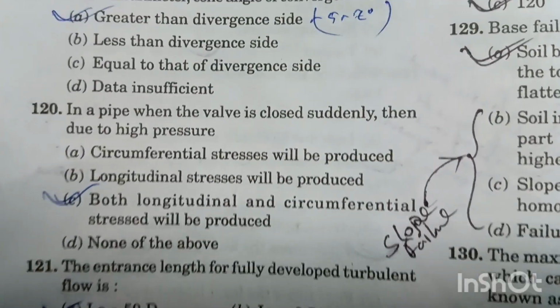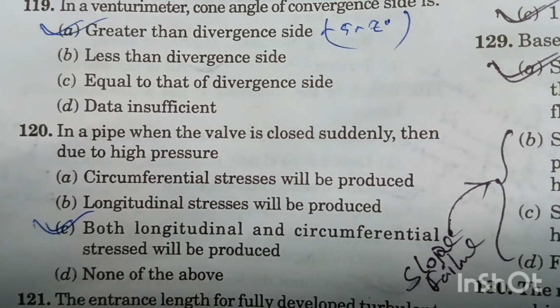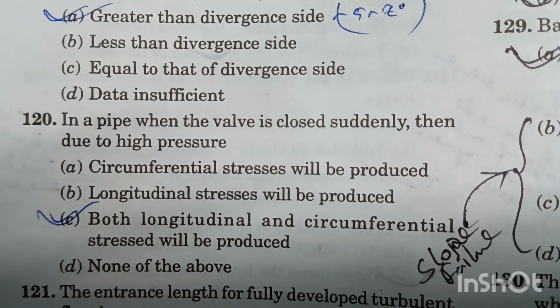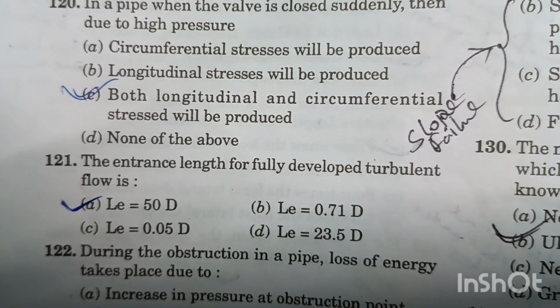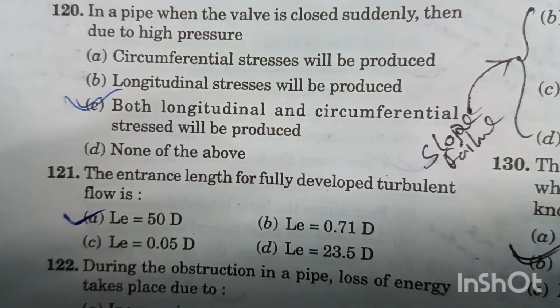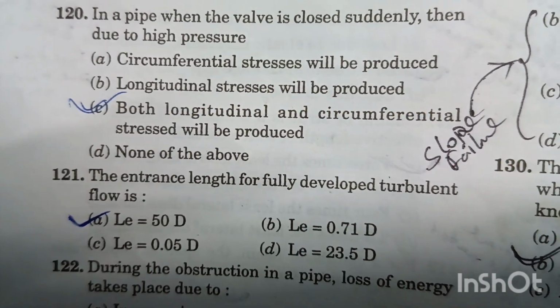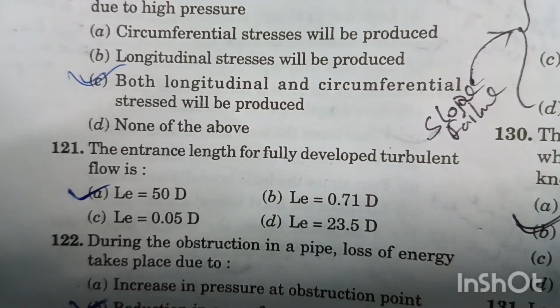Question number 120. In a pipe, when the valve is closed suddenly, then due to high pressure, both longitudinal and circumferential stresses will be produced. Option C is the right answer. Question number 121. The entrance length for a fully developed turbulent flow is 50 d. Option A is the right answer. The length over which the flow evolves to the fully developed state is known as entrance length. Question number 122.